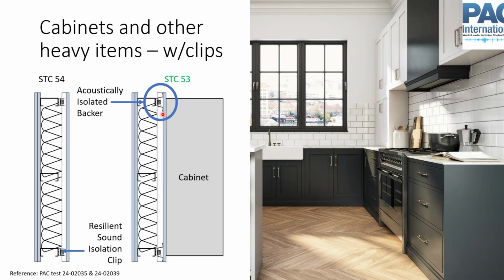So there again are acoustically isolated backers that are designed to work with clip and hat channel systems that maintain your acoustic isolation but give you a stronger, stiffer, more rigid and bigger target to hit to mount cabinets or other things to.